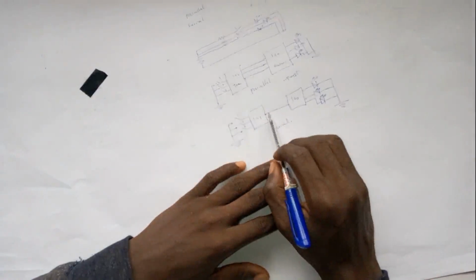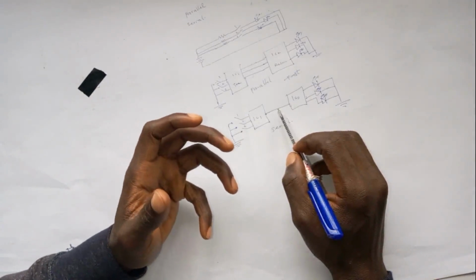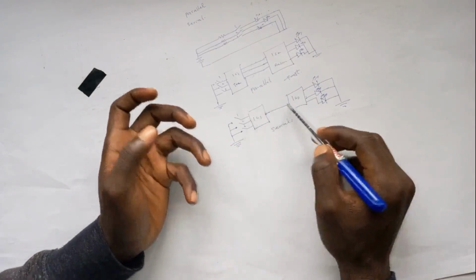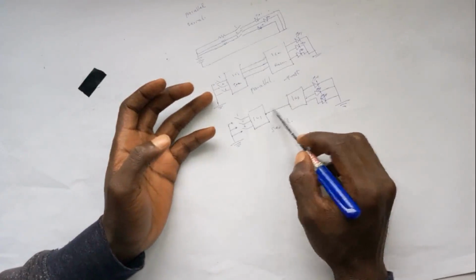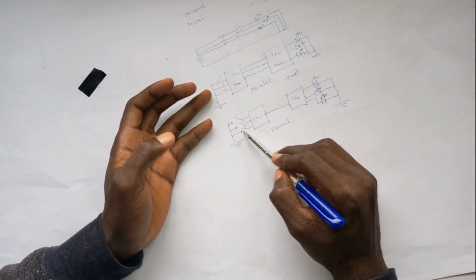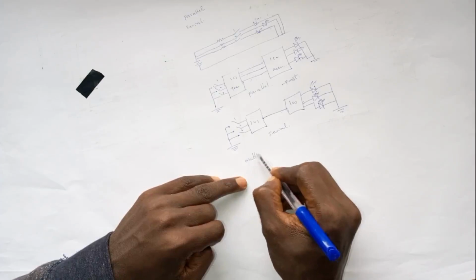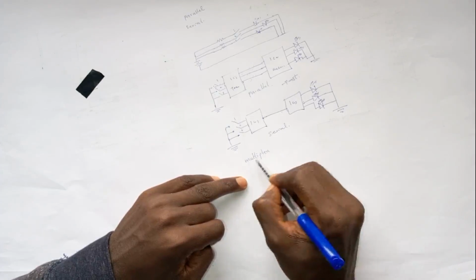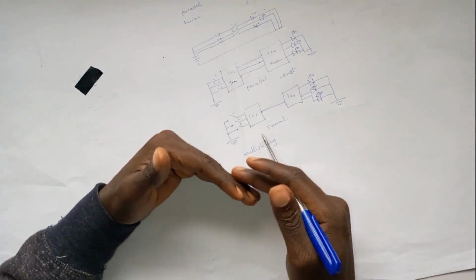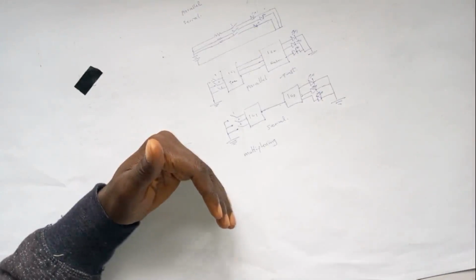So now serial communication. How do you achieve this? Because it's not that straightforward, because instead of having 3 wires, you have 1, and all the 3 LEDs are controlled with different switches. How do we achieve that? We call it multiplexing. So multiplexing is a technique whereby you'll be interleaving the signal.